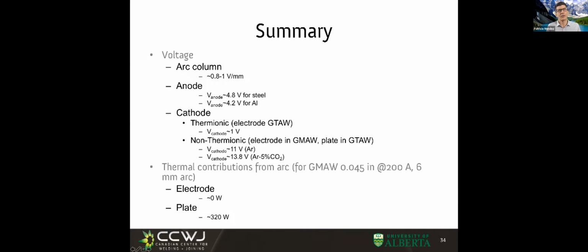Why is it so hot? Because the current that goes through it does resistive heating, and this heating goes out in the form of radiation. And this combination of electrical currents with magnetism creates a force, and the force made a very fast flow of the plasma. So fast that it is faster than a jet plane, right? And that also makes heat exchange by convection. That's how the energy is transmitted in the arc, by convection and by radiation.